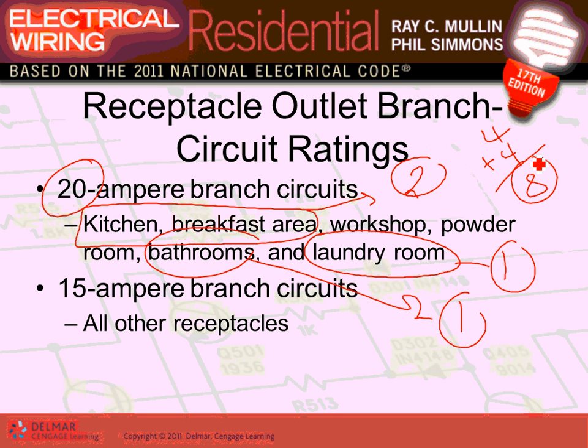Now, would it be a good idea, if you have a garage, to give it a dedicated circuit? Absolutely. Does the code require you to do so? No. Okay. Now, these powder room and workshop, these are up to you. But if you have a workshop, typically we have a 20 amp circuit there to feed that workshop in your basement. Okay. All other circuits are what?